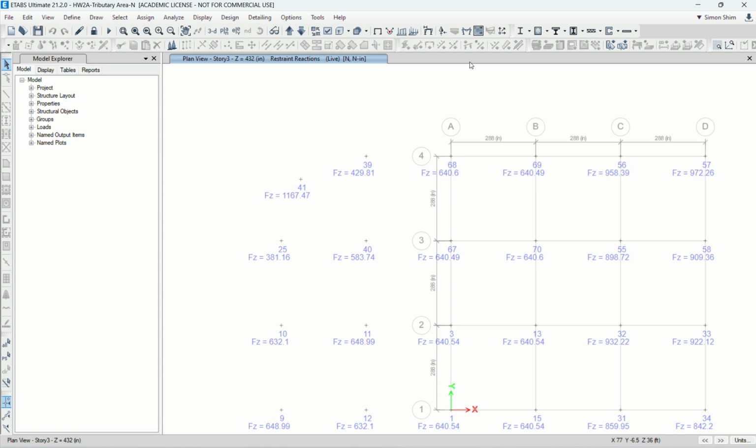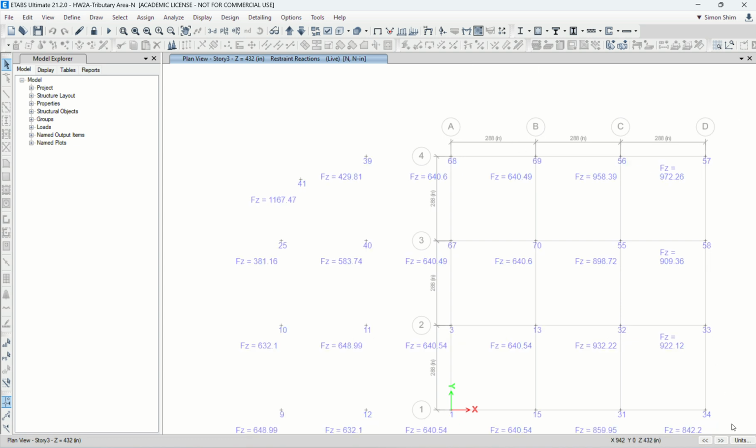Sometimes rounding error is crazy, because 25.4 millimeter, 0.4 millimeter, okay, 1 millimeter. But if you're adding, right? Sometimes you're going to end up with a gap. Construction tolerance kind of thing is happening. So I encourage this: any imperial job, always use imperial from start to end. For metric, start from metric. Because if you convert at some point, you're always going to have rounding error. So unit, good question. But for output, you can change the unit here.